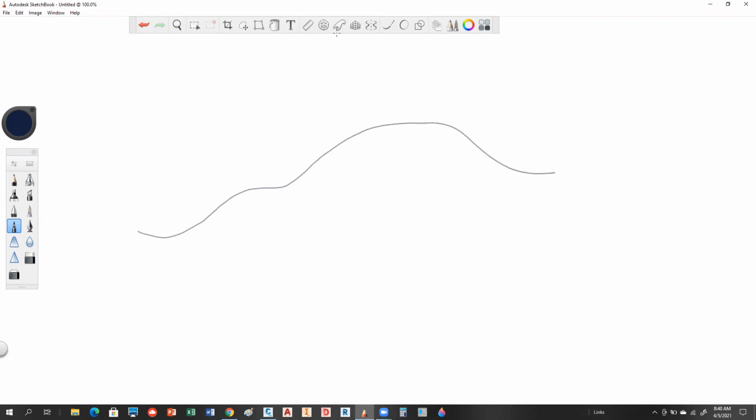So what we're going to do is come in here and design what are called tangents. Now, in horizontal terminology, we call them tangents. Usually in vertical profile terminology, they're often referred to as gradients. That's probably a better term to use. A gradient would tie into something and it would have a slope, and then another slope, like this, okay? So these are called gradients, and some people call them vertical tangents.